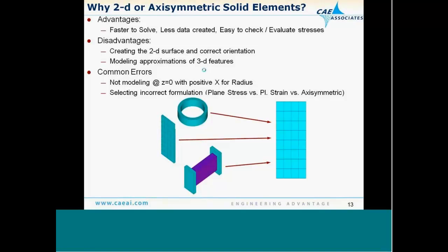And the mesh is just a simple 2D geometric mesh, but depending on, again, the key options we set, this may represent an axisymmetric structure, it could represent a plane stress structure, or it could represent a plane strain or infinitely thick type structure.